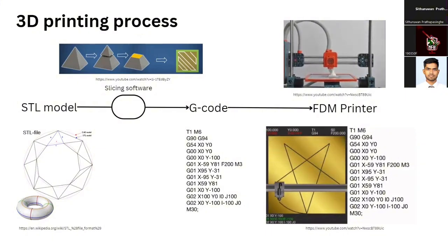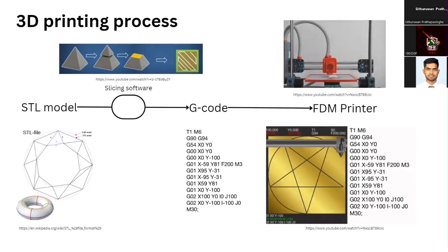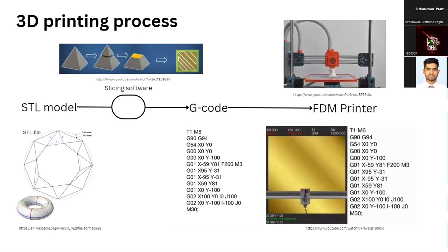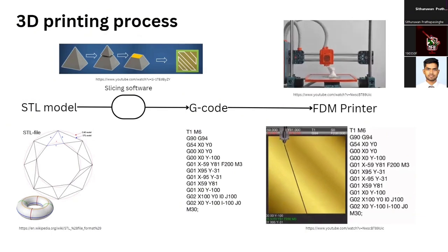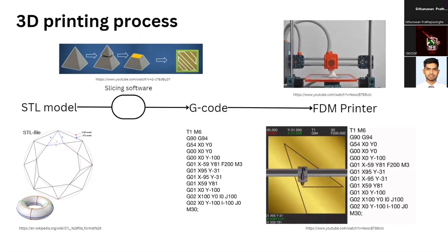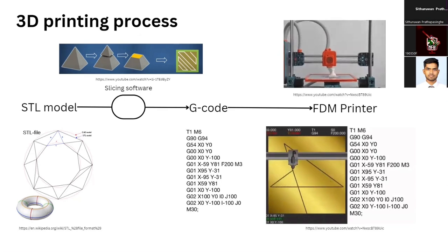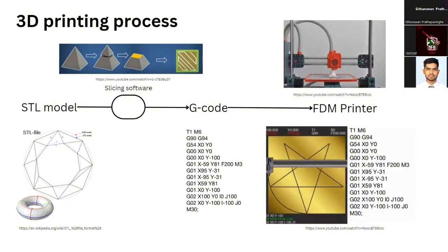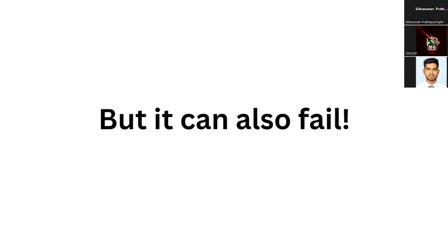Those layers can be translated into G codes, which are the instructions given to the nozzle to perform several motions, like go 5 centimeters left, draw a half circle, or measure the temperature of the nozzle. Those kinds of tasks can be performed directly using these G codes. The collection of G codes can be used for printing the whole object.